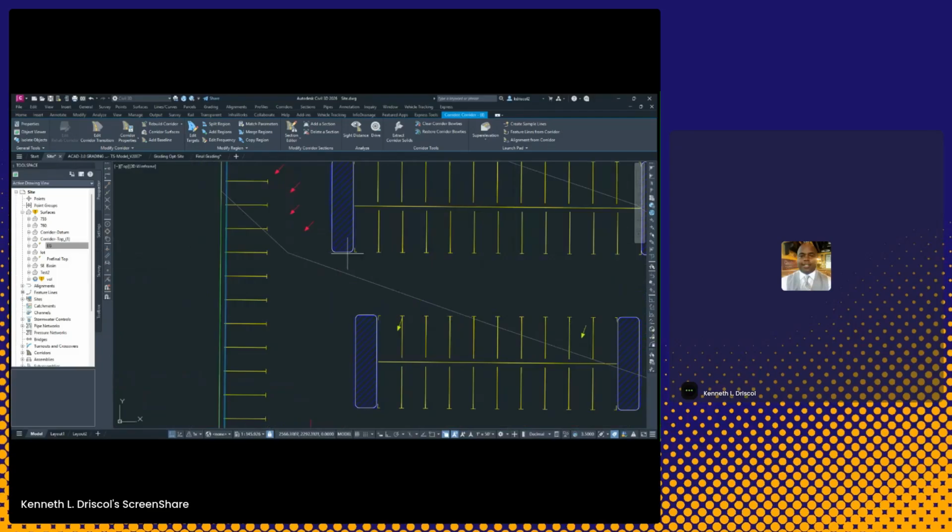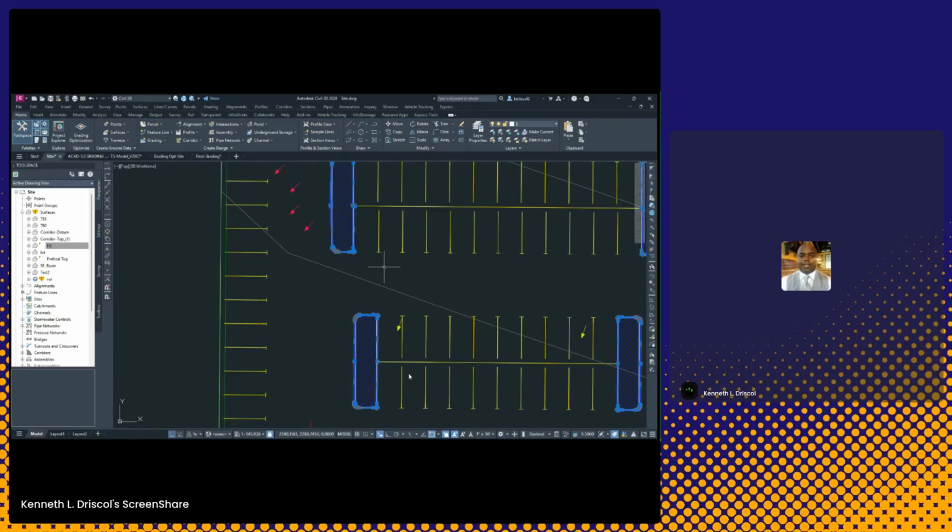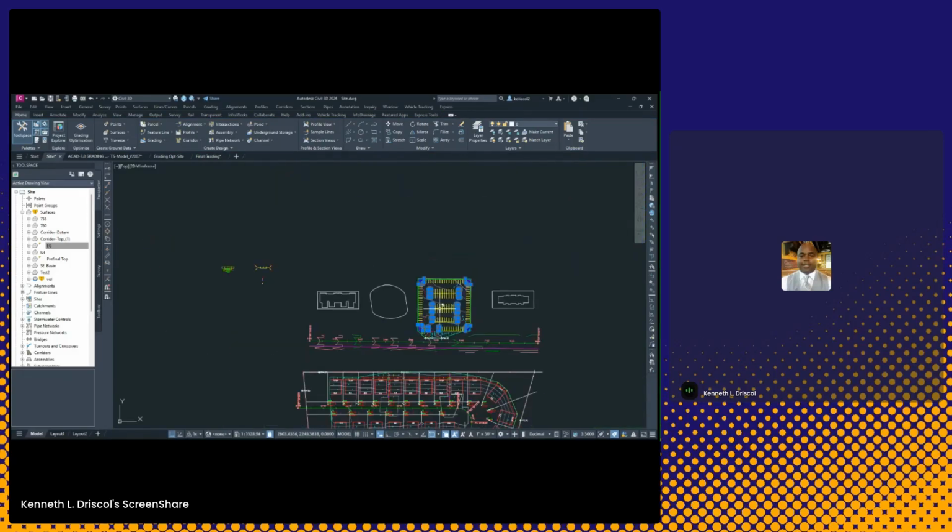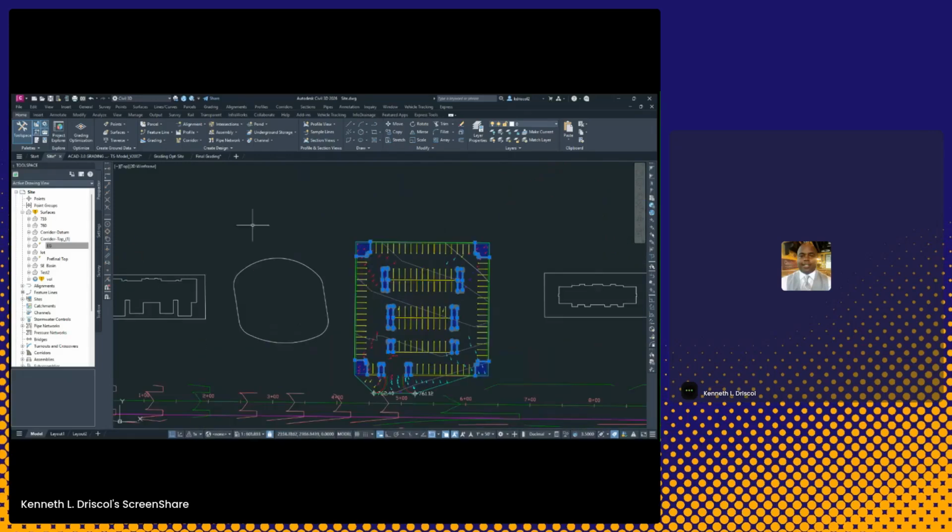From that, I'm going to pick on this polyline, and I'm going to pick on it, polyline, and say select similar. So from this polyline, I'm going to say create feature lines from number. From that, I'm going to say assign that from my lot surface.